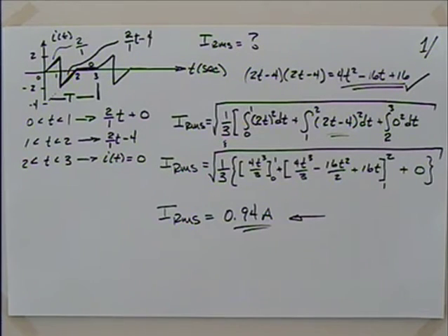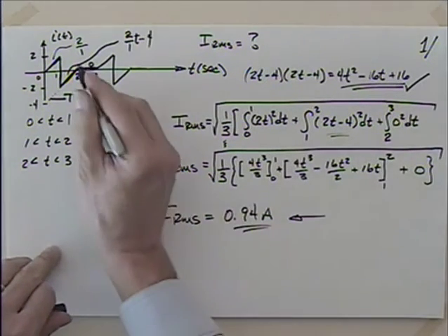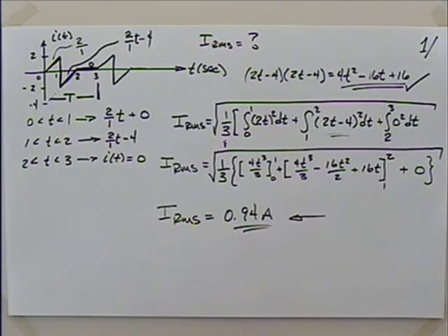And a third of the period is at 0, so we would expect it to be significantly lower than 2, because we're looking at a DC equivalent. Essentially, I don't want to commit heresy here, but essentially kind of a running average of this wave, right? Okay, and this piece here, being at 0 for a third of the period, is going to pull that down.